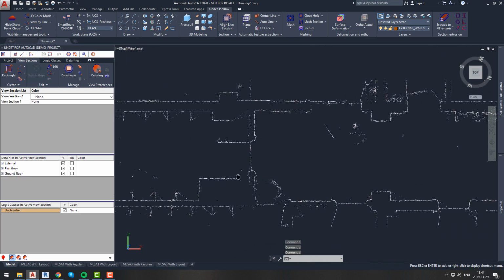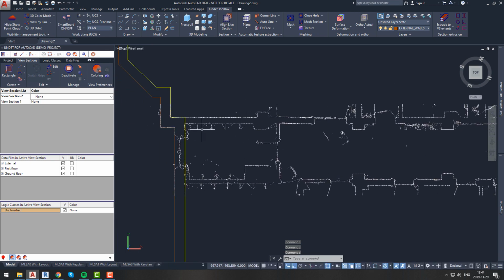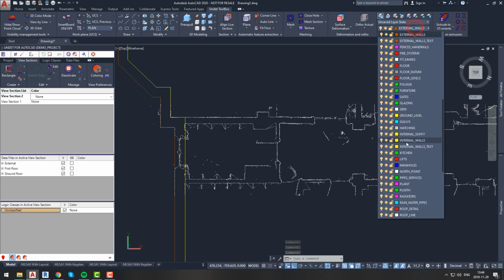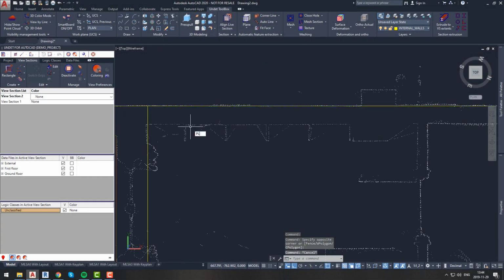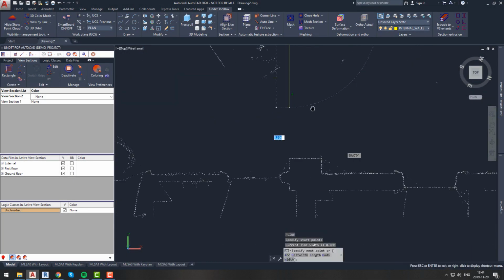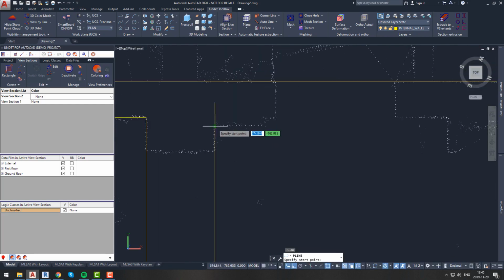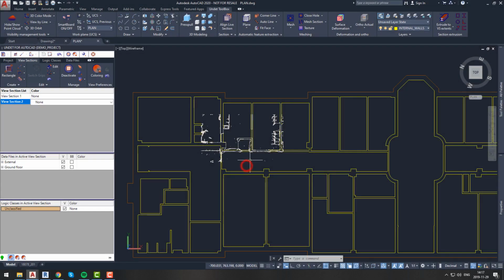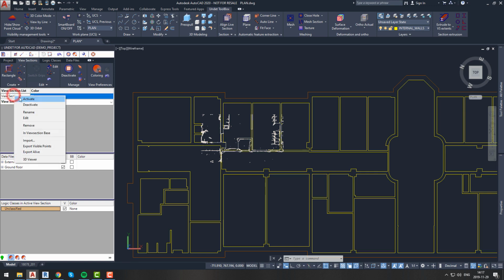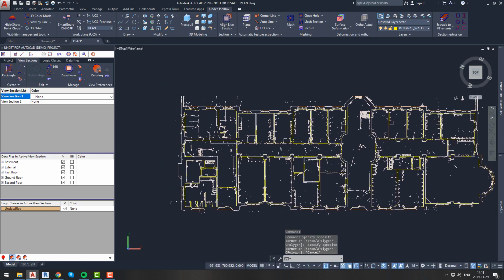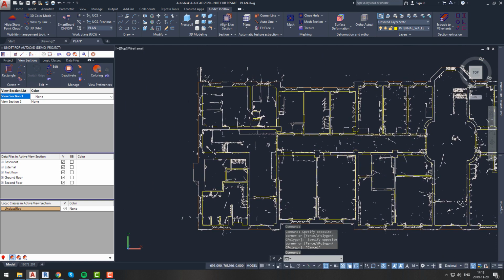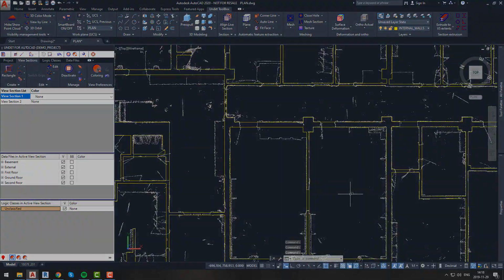At this point we will create new, smaller view section to get better view of inside walls. We also want to work with green indicator as much as possible. Now it is up to you and up to your workflow if you will work with corridor and longest walls first, or you will go room by room, and join everything together after. Anyway we should keep on drawing lines that are in same plane as one long line and then draw additional line. After completing all internal walls we can take a look at our floor plan.